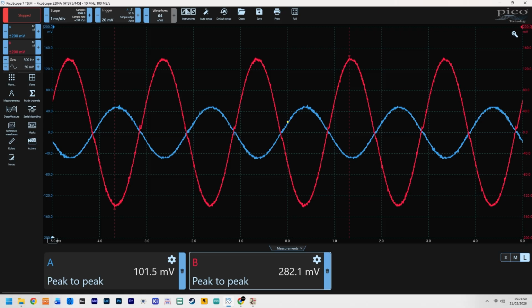As you can see, if you take 100 millivolts and times it by 2.9, which was our gain that we worked out earlier, you end up with 280 millivolts in this case. But again, real world circuits, real world components, that's about right. That's approximately what we designed it for.